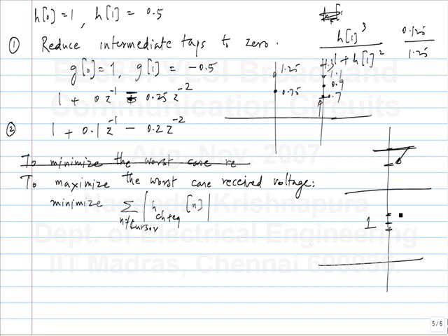Because if all the intersymbol interfering bits are of the opposite polarity, you will get something above that. So to minimize the spread around this one, I can also minimize the mean square value of these points. The algebra is complicated, we will do it later, but that is another possibility. You minimize the mean square value of the possible responses to 1.